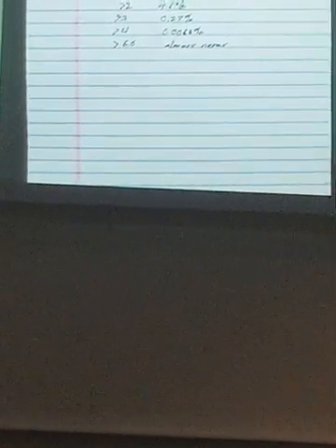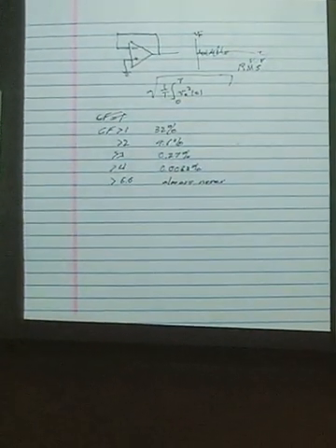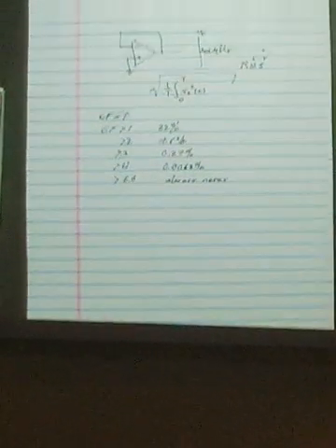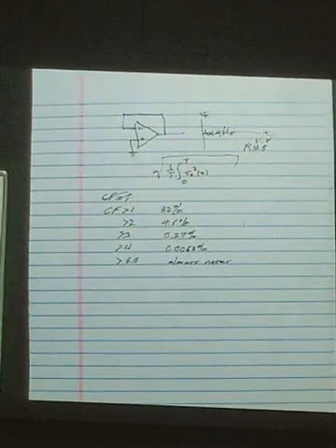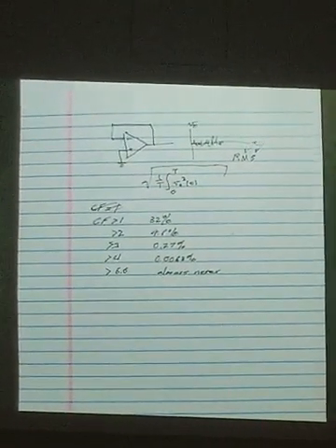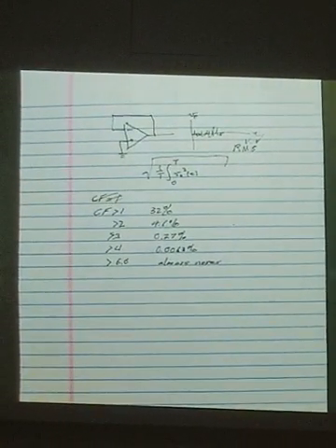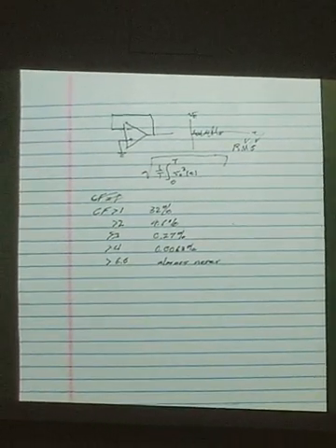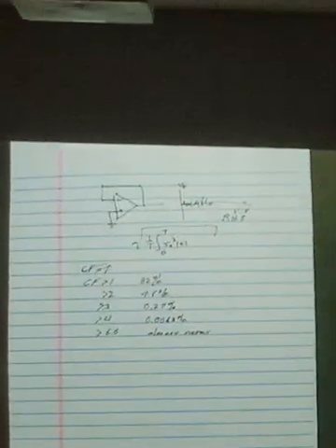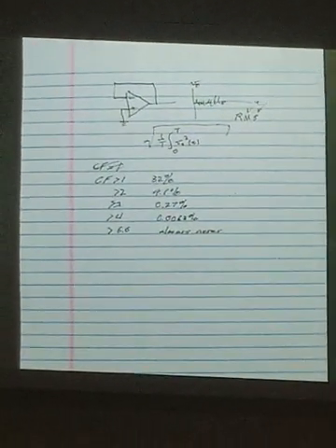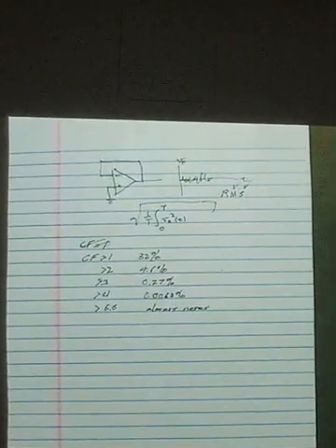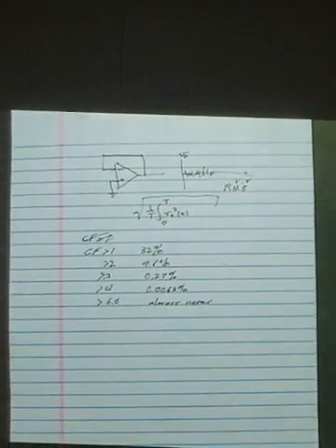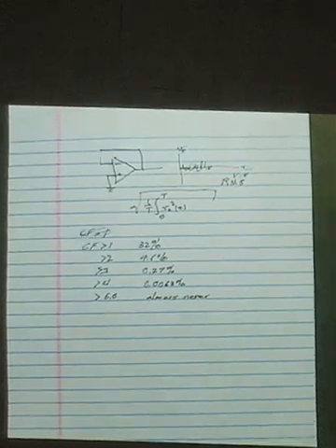You want a signal which is, think of it as this peak to peak amplitude of plus and minus 6.6, to still fit in the input range of your AD after being gained up. And if you get something that's a little bit bigger, you won't blow the input protection on your AD converter.